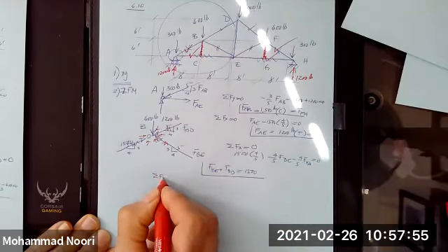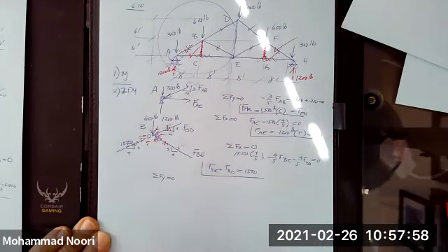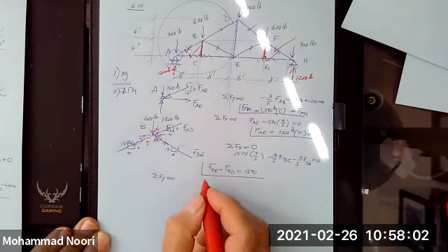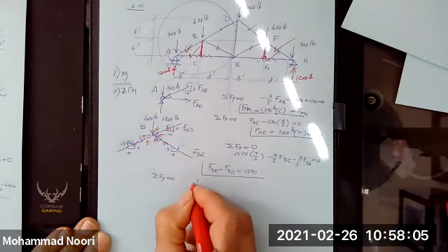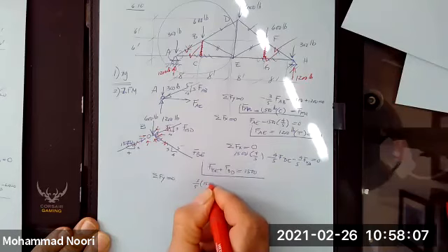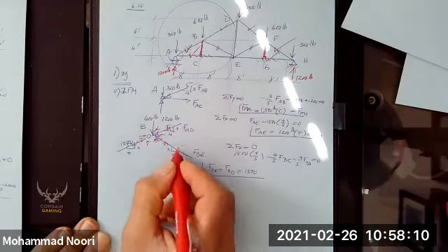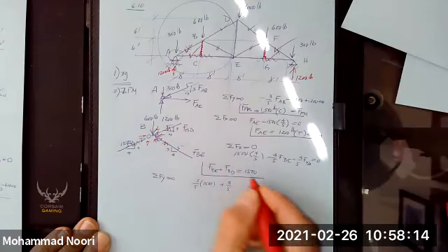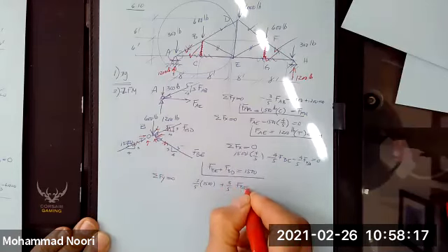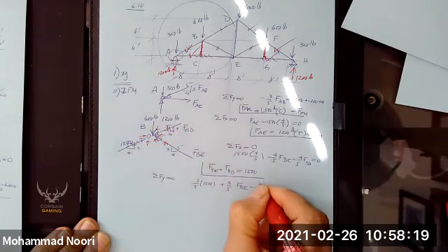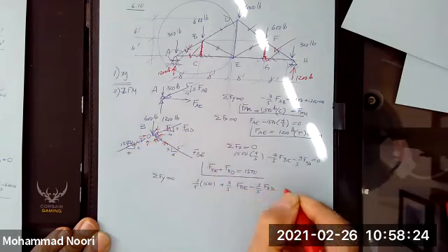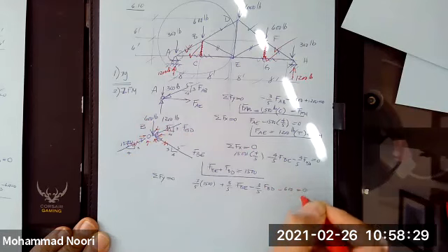Write the summation of forces along Y is equal to 0. Okay, these components, you get 3/5 of 1500, this force, then plus 3/5 of FBE. For this one it is negative, so negative 3/5 of FBD, and then you have negative 600 equal to 0.